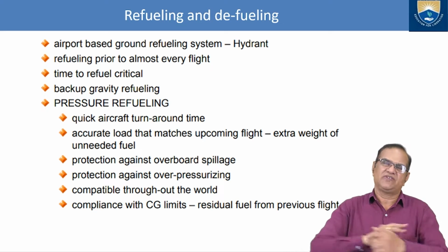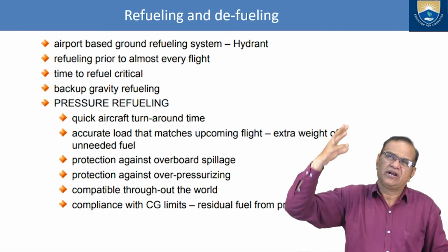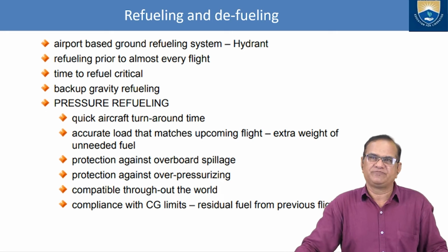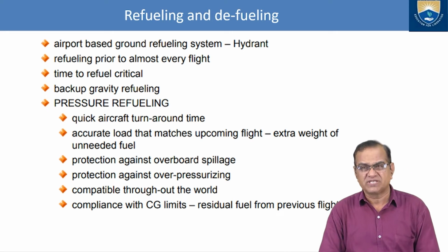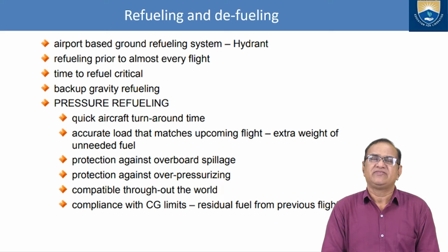Backup gravity refueling. Sometimes if it is not there, we put a big, very long tank, and from there the fuel can come without any pump. Another is pressure refueling. In this we use pumps.